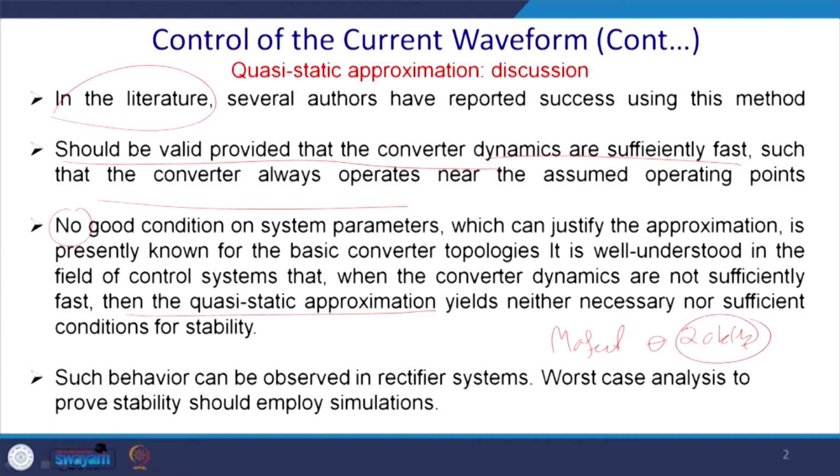Now, because of a higher power rating, you want to design the same entity, a buck converter or boost converter, generally a boost converter as I discussed because it is easier to implement, and you want to make it with a GTO. Instead of 20 kilohertz, you require to operate at the sub kilohertz level, maybe 500 hertz.